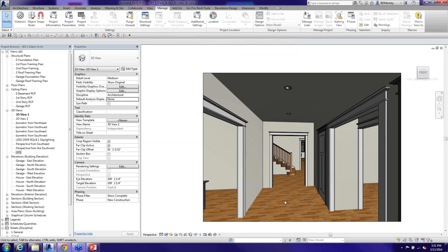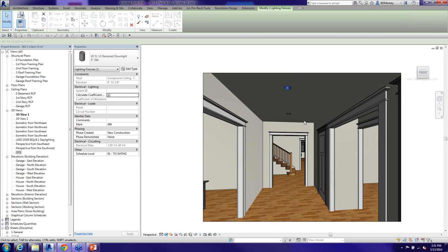Well, now let's get into lighting. If you have lights modeled in Revit, and there is a light source to that light, Revit is going to use that object's light source. A lot of times you're going to see that I'll be in realistic mode here, but the realistic mode is not picking up on lighting. Realistic is picking up on material renders, the little JPEGs, but not lighting.